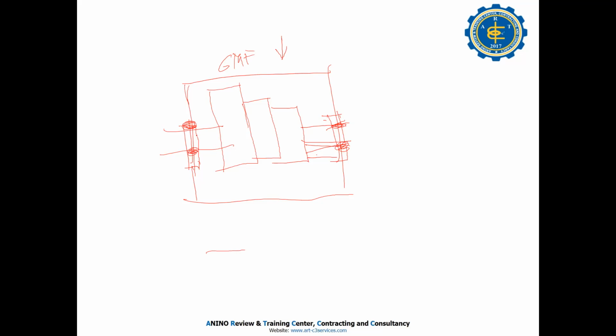Now, if your bearing has a problem, starting to damage, what happens to your gear mesh frequency? It goes up, your sounds go up.